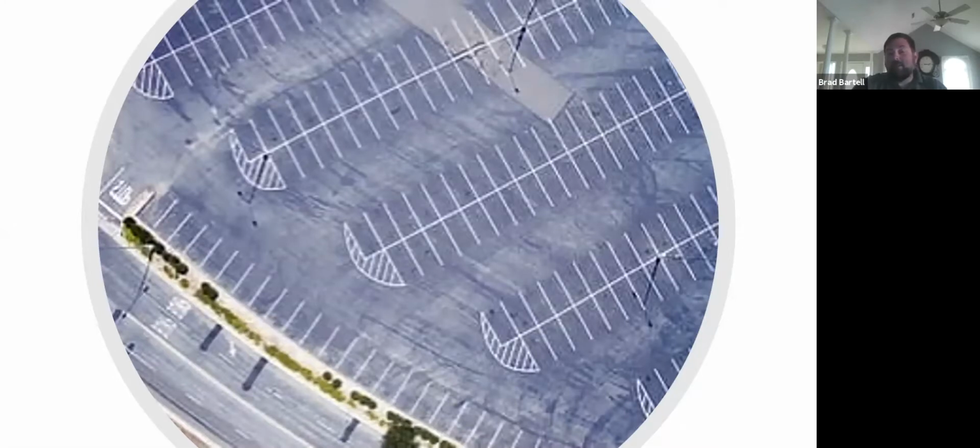I mean, a whole parking garage, you figure a drone is doing a 10-acre area in about 5 minutes. And then you can take the imagery back in, you can draw off of it, and that's way faster than you can survey it. That's depending on what you need on there. If you need mapping grade, you've got it there. If you need to go survey grade, we're going to have to do a little more to it to bring it into that.